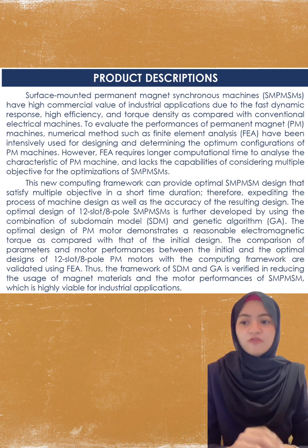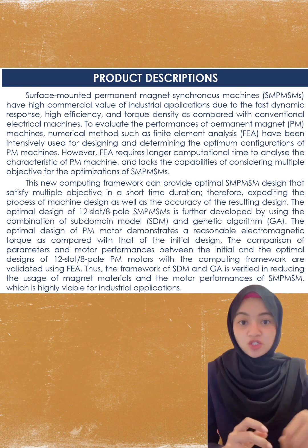The comparison of parameter and motor performances between the initial and the optimal design of 12-slot 8-pole PM machine with the computing framework are validated using finite element model. Thus, the framework of subdomain model and genetic algorithm is verified in reducing the usage of magnet materials and the motor performances of SM-PMSM, which is highly valuable for industrial application.